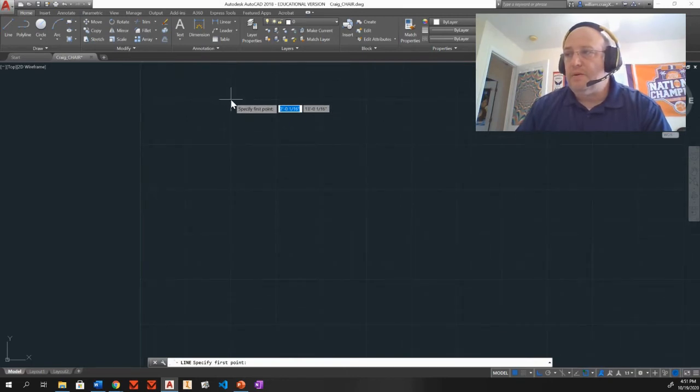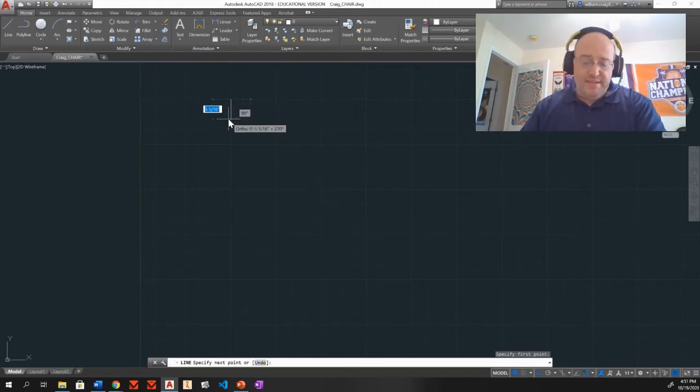and I'm going to select a point about where one of these crosshairs are. You can see that I'm actually floating around a lot. This has to do with my settings to set this file up. My snap is off, but my grid is on, my ortho is on, and my O snap is on. My O snap, I have everything selected correctly. So it gives me a little more freedom to move around.